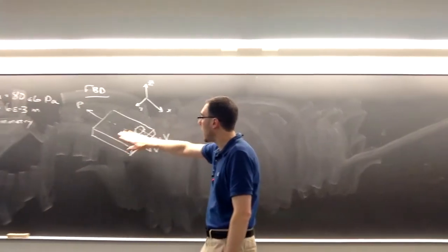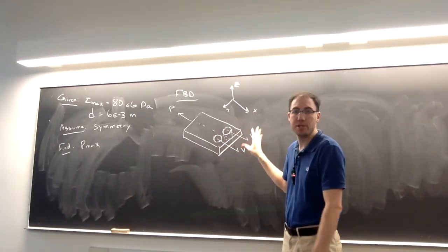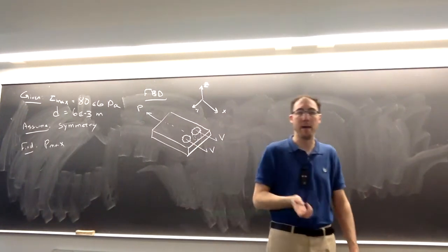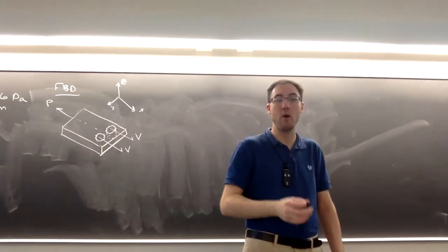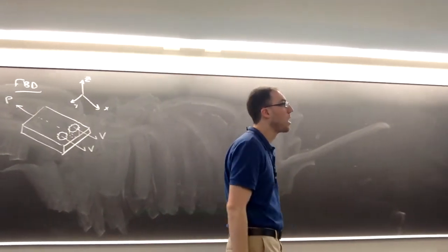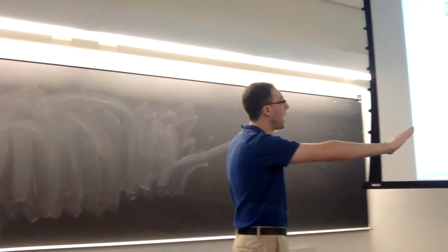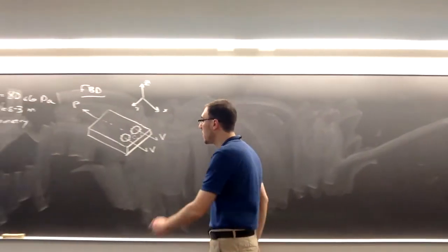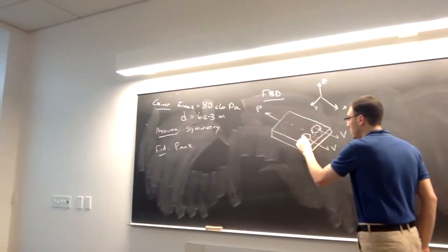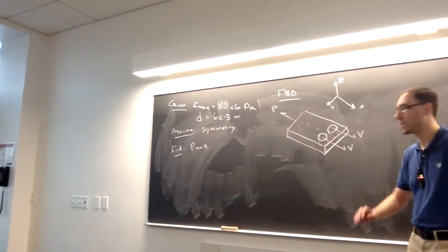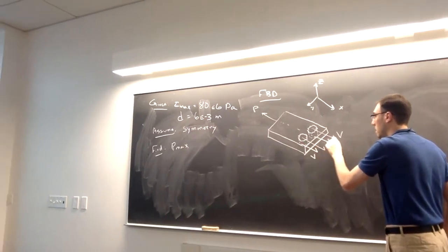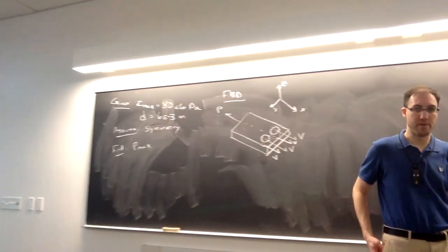So I cut through the top here, and I only drew the two internal shear forces. I ignored for the moment the bending moment and the normal force. But I'm also making a cut at the bottom of the piece of wood through the other side of the bolts. So because I cut through a second surface, there's also a shear force on that bottom surface.